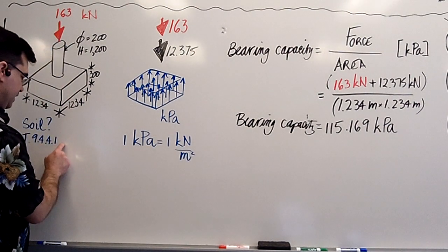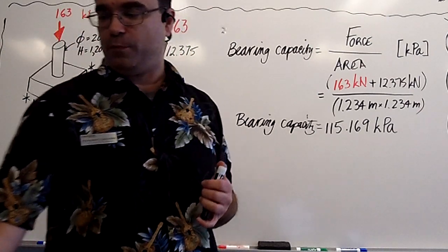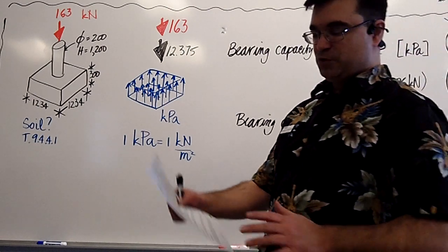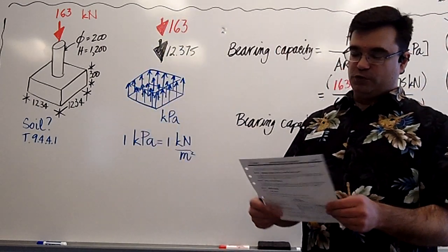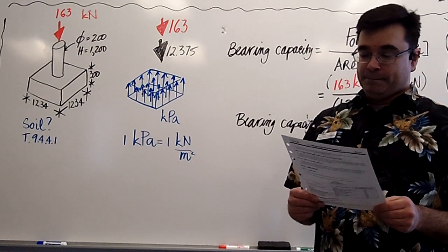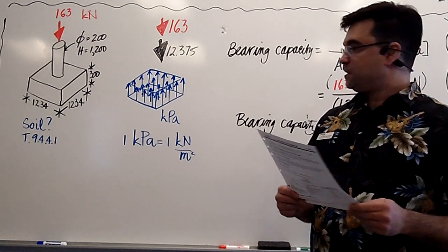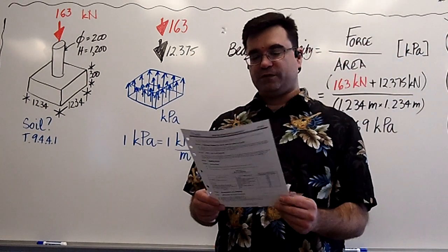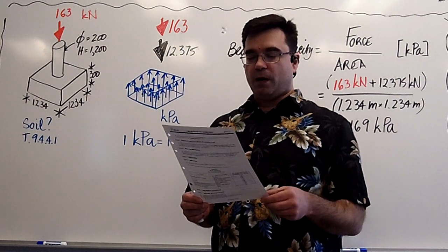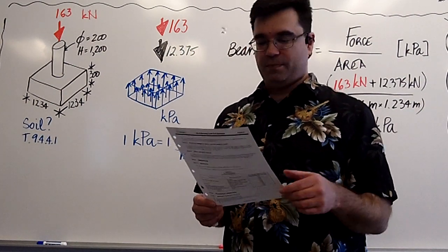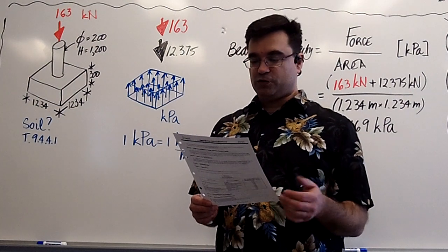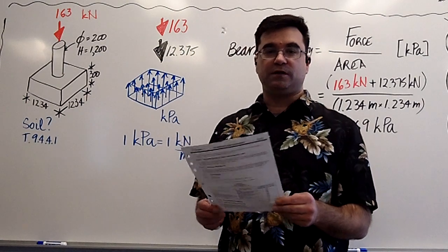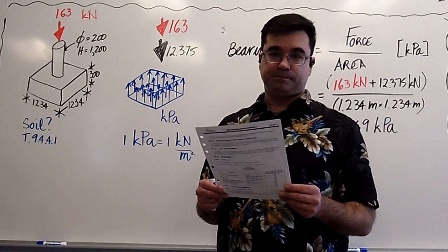So then, let's go here in table 9.4.4.1 and see which soil gives us those values. So that's what I did. I grabbed that table for the Ontario Building Code, Part 9, and I look for anything that is bigger than this. And I find a few, right? Just off the top of my head, I'm seeing dense or compact sand or gravel at 150 kPa, stiff clay at 150 kPa, and then there's till, clay shale, and sound rock that are even larger than that.